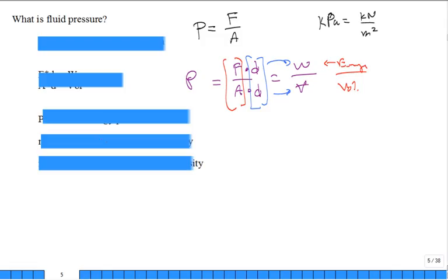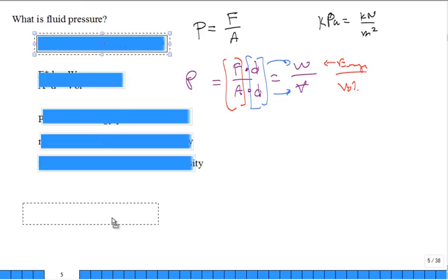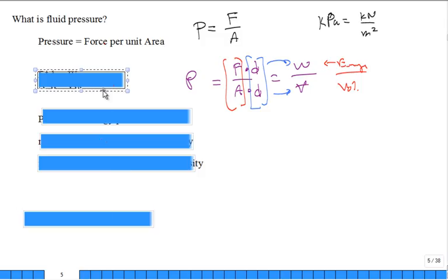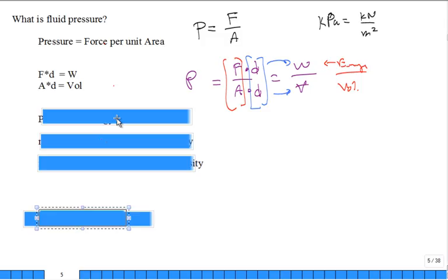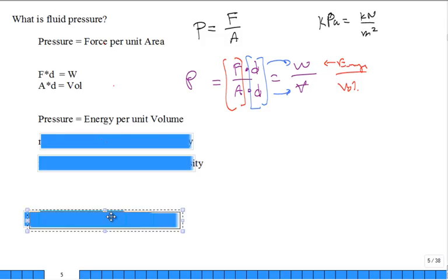So let me uncover the same things that I just talked about here. Okay, my computer will obey me. And then, what do we pick up for pressure? It's energy per unit volume. That's probably new to you, right? That you can think of the pressure as the mechanical energy of the flowing fluid, because it's associated with the flow work when it changes pressure going through the device or across the device. And you have the energy per unit volume.